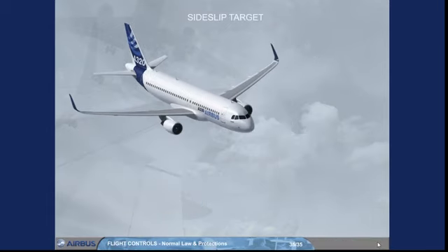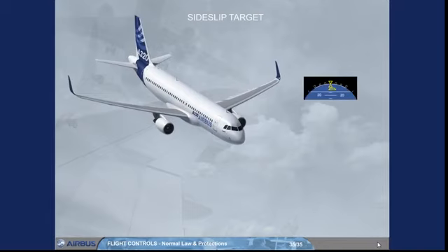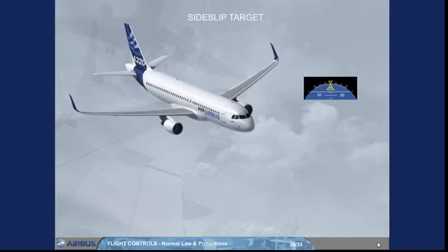In manual flight, if one engine fails, the FAC modifies the side-slip indication displayed on the PFD in order to show the pilot how much the rudder has to be used to obtain the best climb performance, with ailerons at neutral and spoilers retracted. The side slip target will change to blue if the engine fails during takeoff or go around. Note, when it is blue, it is called beta target. For more information, refer to your FCOM, ATA31 or DSC31.